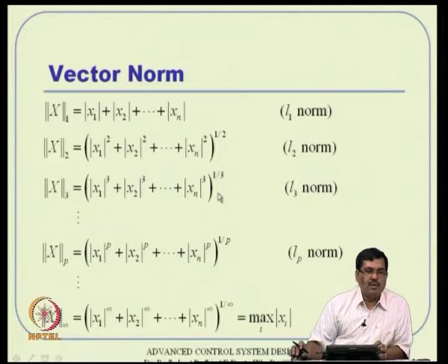That theorem is a very handy tool which tells us that we will not have to worry about each of the definitions individually. Most of the time we will deal with the second norm. All the LQR theory, quadratic things, and the Kalman filter, all of these we will talk about as an H2 idea. Sometimes these are called H2 norms also; H comes from Hardy space and all that, and I will not go too much into that. Either we deal heavily with the 2 norm, or sometimes we like to deal with the maximum quantity of the noise and things like that.